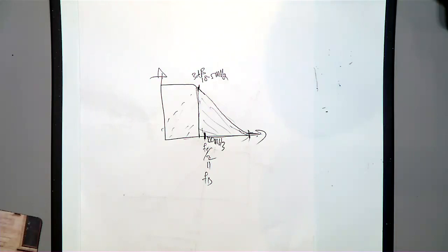Yeah, so for the DSO, please make sure that your 3 dB is between 18 and 20. You can't put it at 15, not a good design. But the stop band, we don't usually evaluate how much it is coming, because it depends upon your order. But in order to get a sharp stop band, don't go for a 10th order filter. Maybe 2nd order or maximum 4th order might be good. 2nd order might be ideal because of the space requirement. If you are interested in 4th order, you can go ahead, but 2nd order will be good.